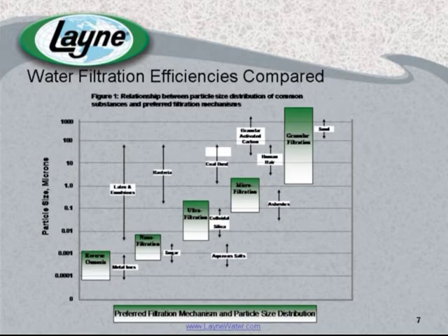Having said that, there is a very broad range in each one of these filter applications or technologies. So you can use more of the traditional granular media, or you can choose microfiltration or ultrafiltration. And you can get similar results, and perhaps both would work in your application. And that's where we really need to look at some of the other parameters, because if you simply look at finished water quality, you'll have several different options potentially available to you.